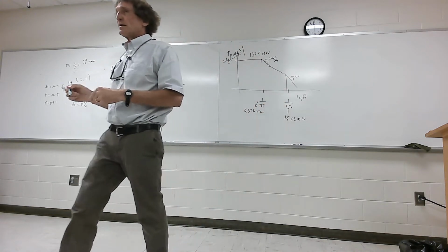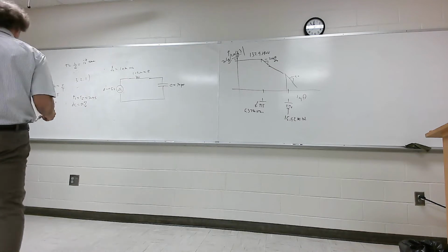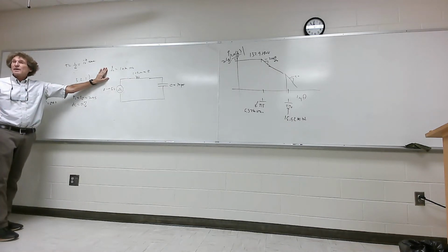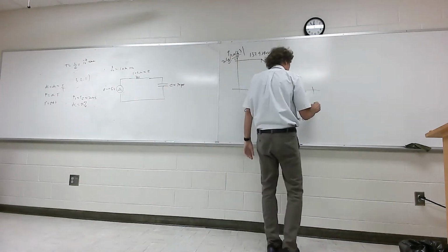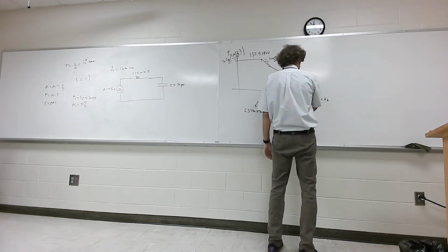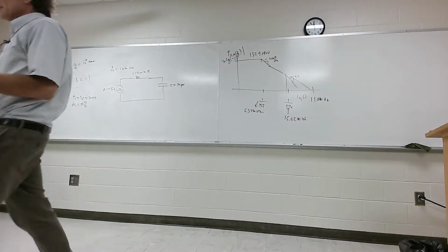Now we have to locate the frequency we want the value at of the source voltage. That was the 11th harmonic, right? If the actual fundamental is 10 megahertz, the 11th would be 111 megahertz. Y'all follow? So I come way out here to 111 megahertz, or 110 megahertz, pardon me. And that's where I want this value. So now we're going to get that value. Please just make sure you hear and understand everything I said.